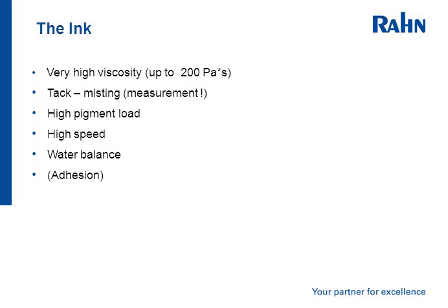The ink is generally a very high viscosity, up to 200 Pascal seconds. Litho inks have a unique measurement called tack, and also suffer more from misting, and these two elements will be described later. It has a relatively high pigment load required because of the low film thickness.